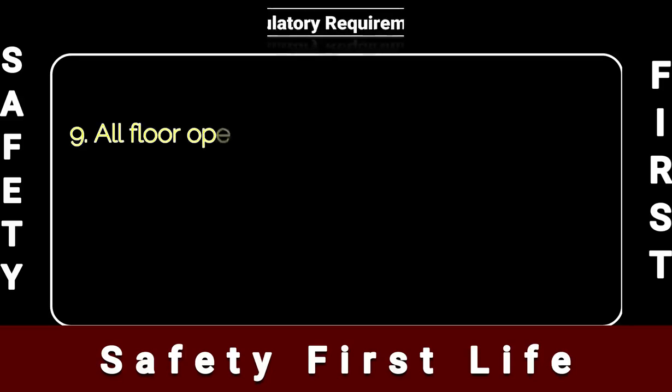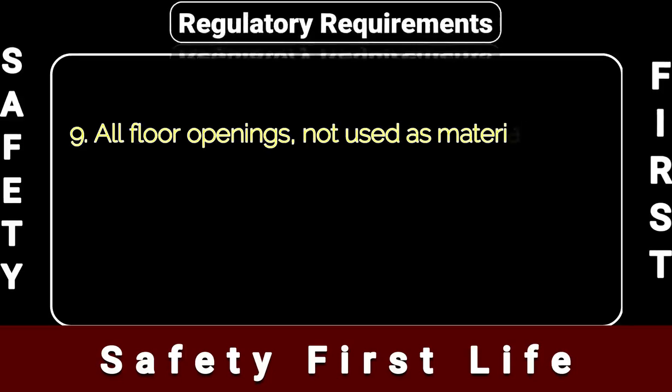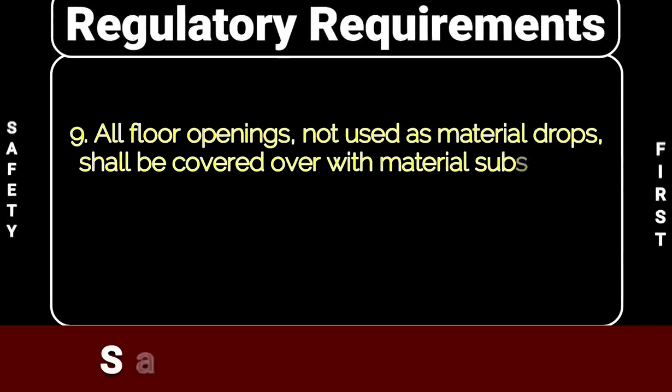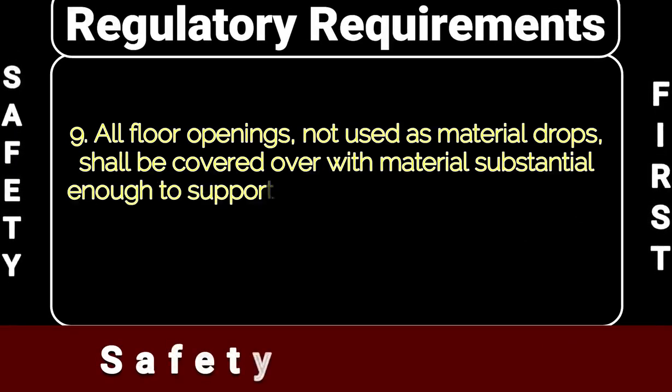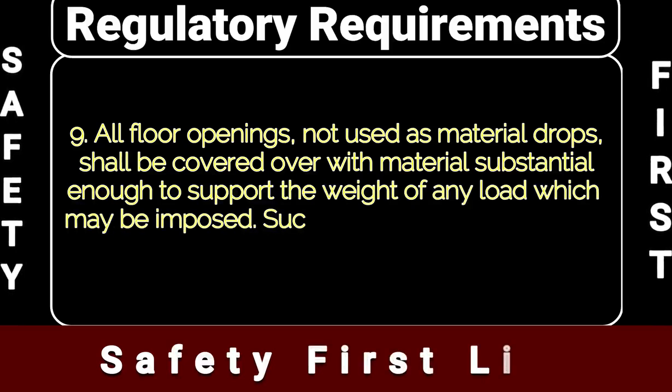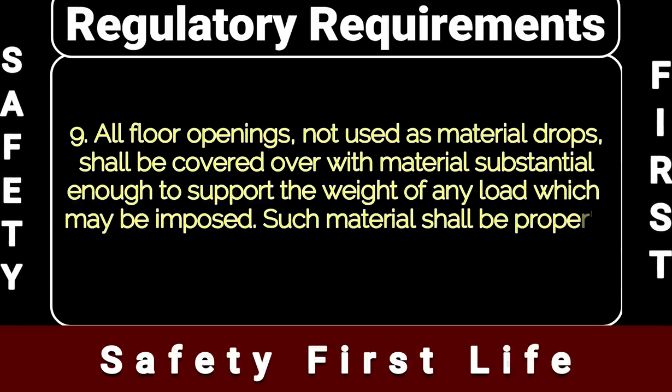Number 9, all floor openings not used as material drops shall be covered over with material substantial enough to support the weight of any load which may be imposed. Such material shall be properly secured to prevent its accidental movement.